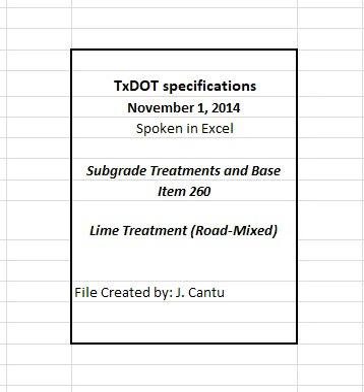4.2 Pulverization. Pulverize or scarify existing material after shaping so that 100% passes a 2.5 inch sieve. If the material cannot be uniformly processed to the required depth in a single pass, excavate and windrow the material to expose a secondary grade to achieve processing to planned depth.